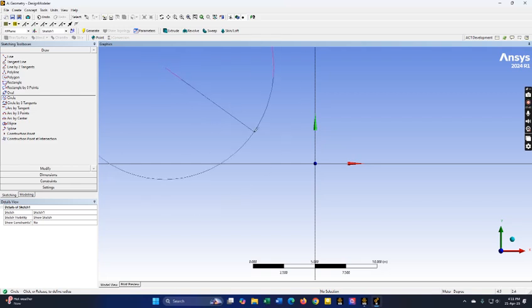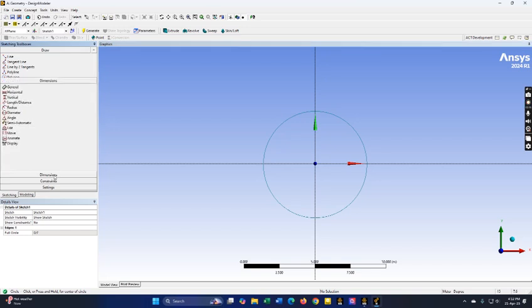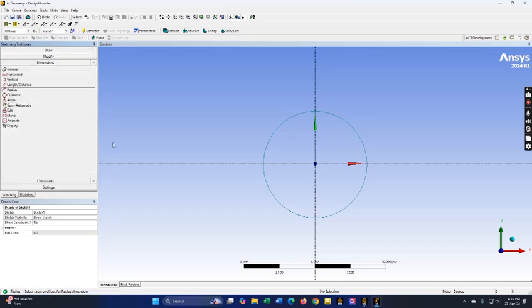Alright, my bad, escape. So choose this center, and we are creating a circle. Choose this center until you see the C or P. You can see C at the center of the axis. So unless you see the C, do not select that point. After you see the C, choose the circle and give it a dimension. Again, this dimension is based on what our professor has mentioned today, which is 0.075.